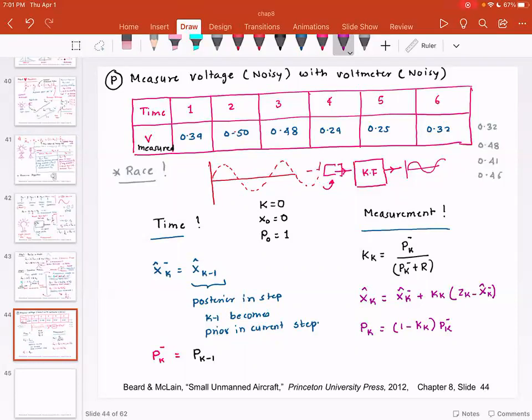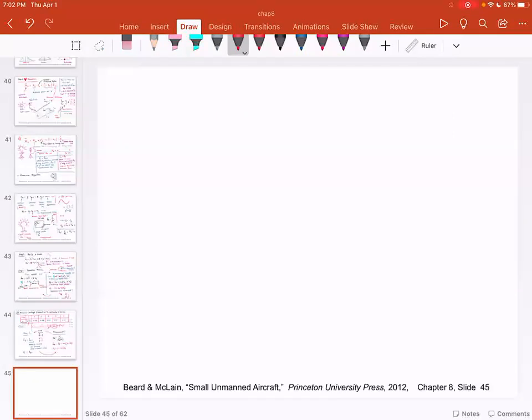Now here is what I'm going to do. I'm going to take this value as my first value, and I will calculate this iteration by hand. I'm going to do this whole iteration by hand, and I hope with powerful software like MATLAB, you'll be able to get the answer quicker. Some of you may ask, what do I put in the matrices for the Kalman filter block? In your Kalman filter block, you have to put A is equal to 1, B is equal to 0. Then obviously you have C and D. You don't need to put those because there is no direct update from the sensor, so you can uncheck the block on the input update.